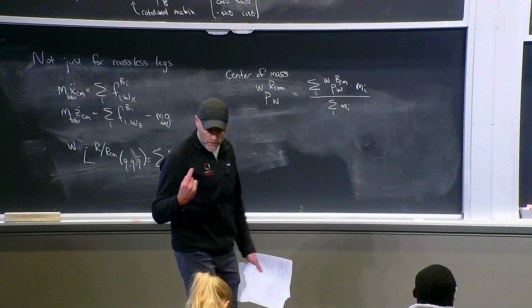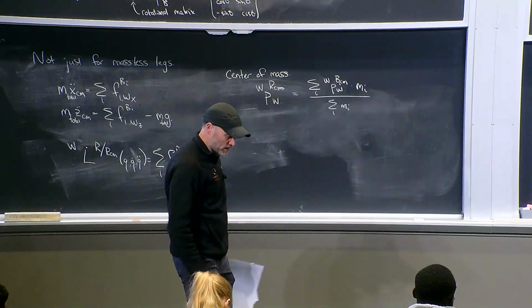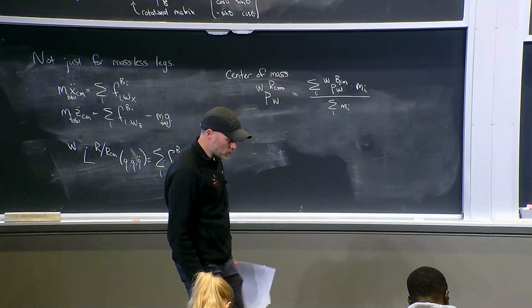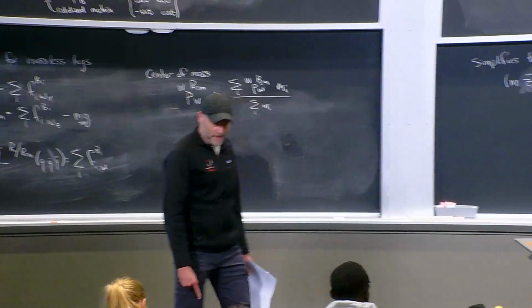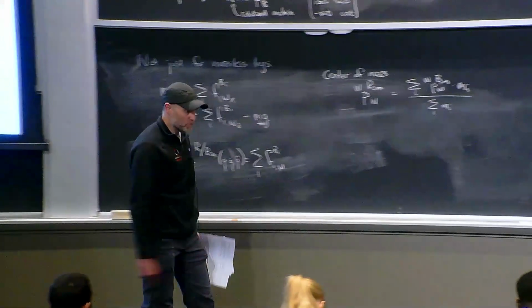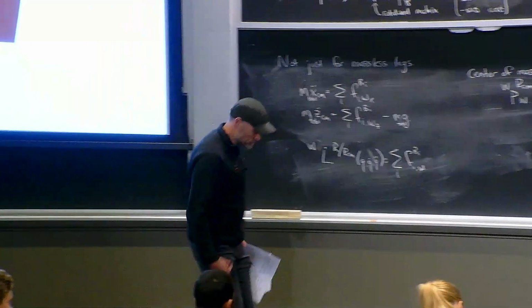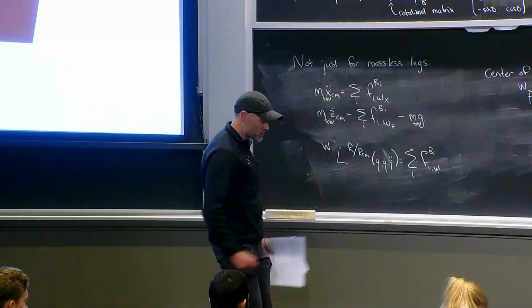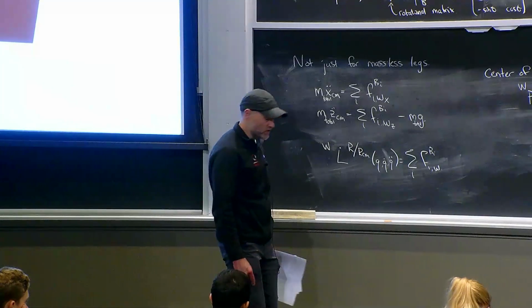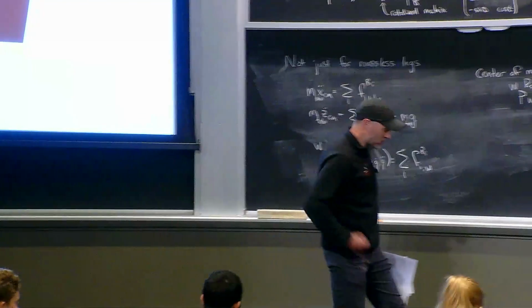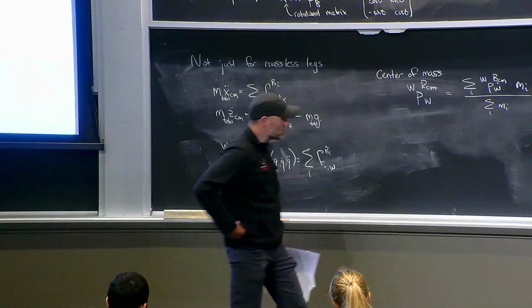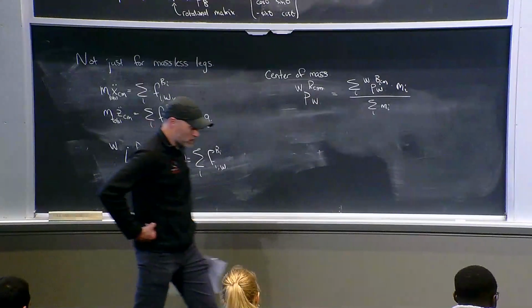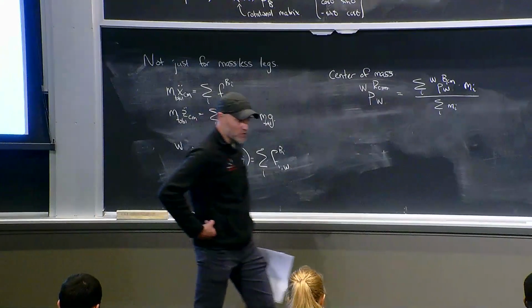It's interesting. If you think about those early walking robots, and still actually a lot of the walking robots today, there was a debate at the time between whether you needed force control in your legs or whether you could get away with position control. And the Asimo-style walkers actually used only position control in the legs, and they basically said, even though my goal is to control my ground reaction force, there's a simple relationship between my center of mass dynamics and my ground reaction force.